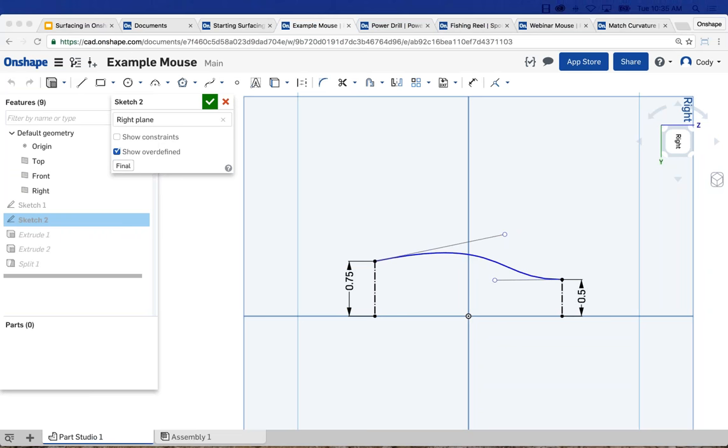Question: can you make a projection curve without having to go through all these steps with these surfaces? No. Today we extrude the surfaces up to each other. Now it has been brought up in the past, kind of a composite, bringing the two curves together. But as of today, generating that edge would be done using the technique I showed you.